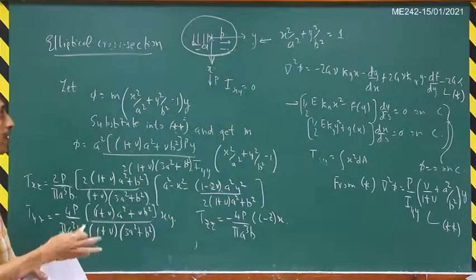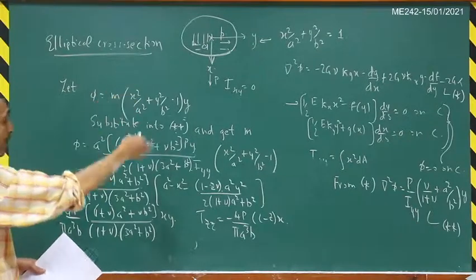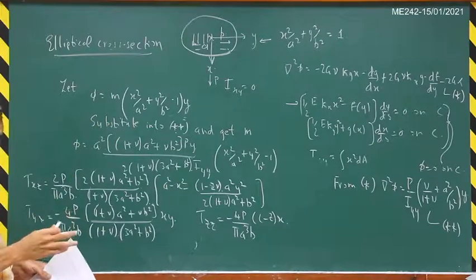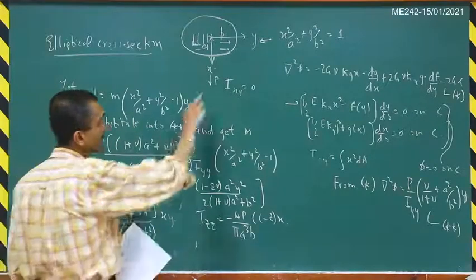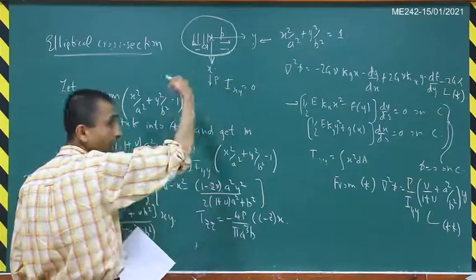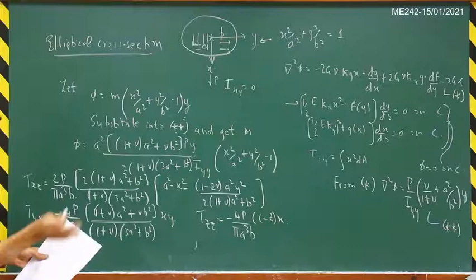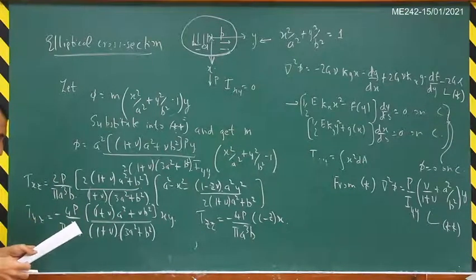Again, in an actual situation we will not be able to apply the traction according to this distribution. Then we have to use that Saint-Venant principle, that basically we are getting a resultant load P through a different traction distribution. Then make use of this Saint-Venant principle, that away from the area of loading the solution will be almost the same here.